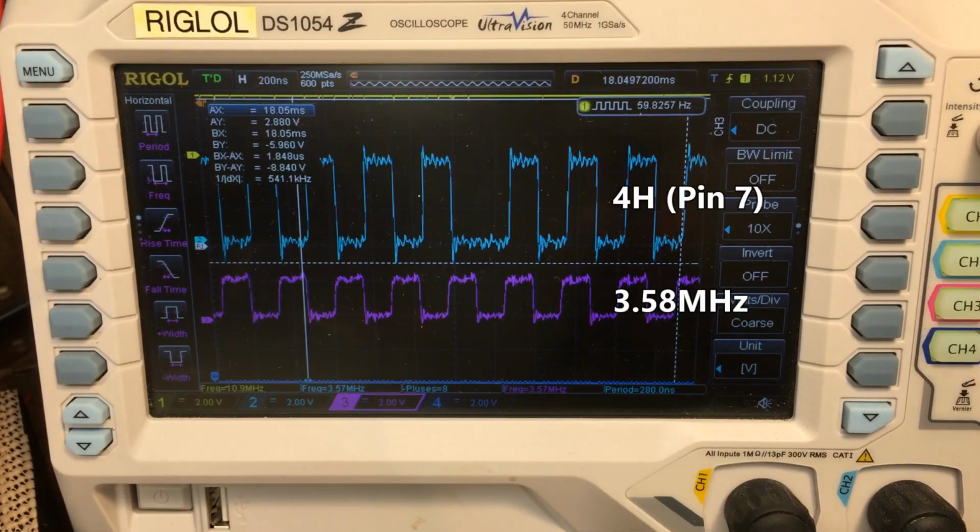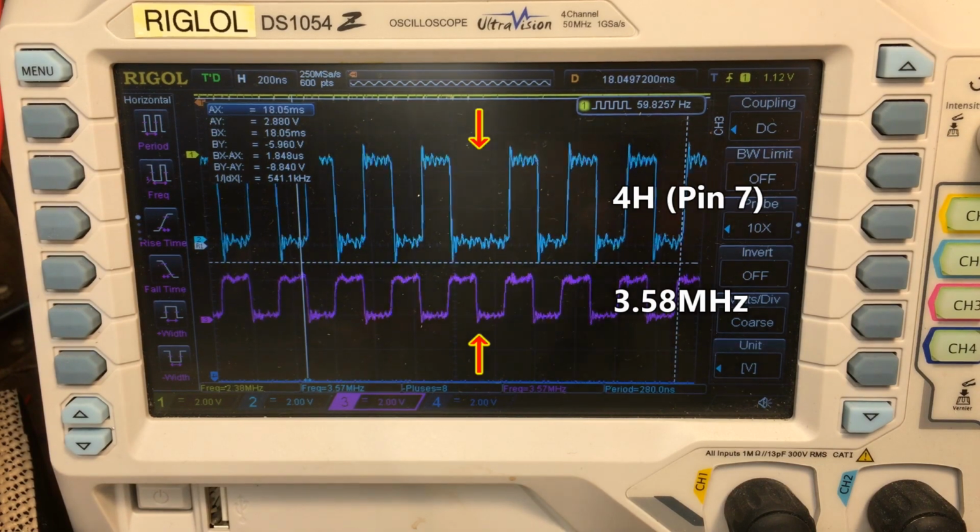Let's look at it on the scope compared to pin 7 from the horizontal counter. You can see that the phase changes relative to the free-running clock at line boundaries. With our reference signal built, now we need to make the actual color burst signal.